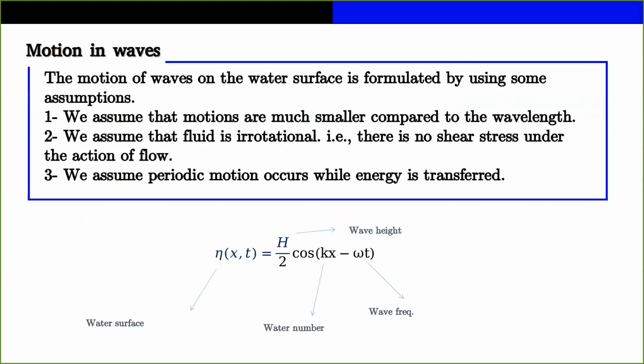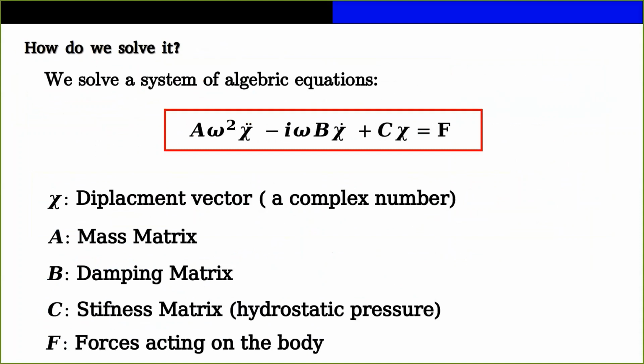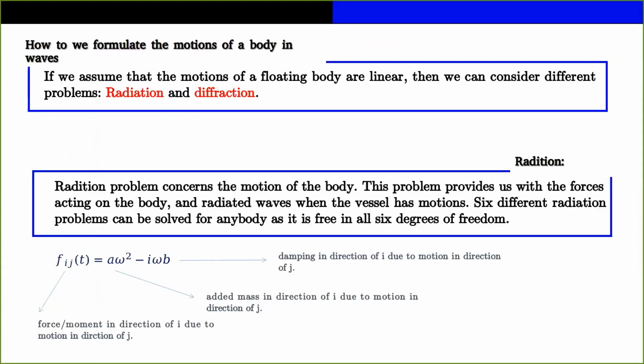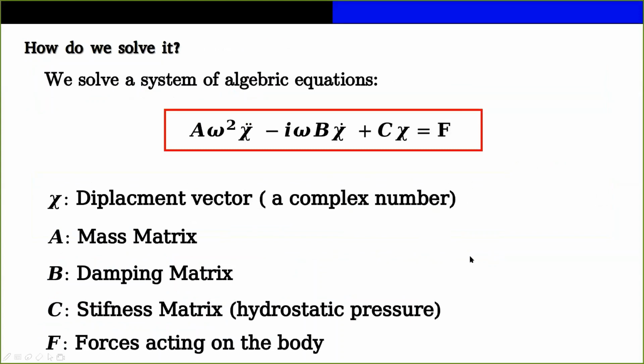By the way, if we solve the radiation problem for the case of a floating object, we can use it to solve its real motion in the sea. So we don't need to solve its dynamics in the wave. We can use the simulation of the radiation problem to solve this equation, and we don't have to solve a real 6 DOF problem. That's how it works.